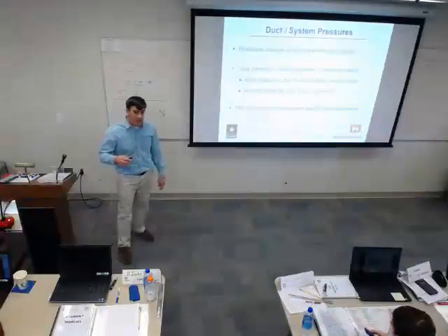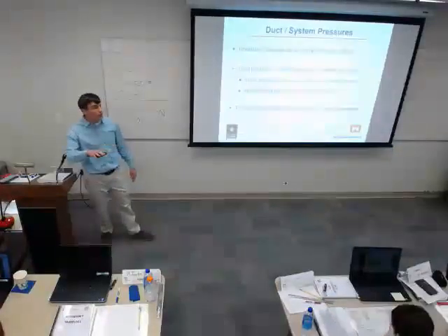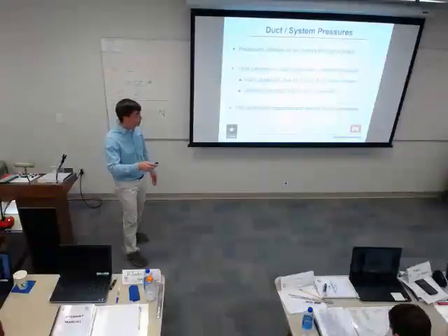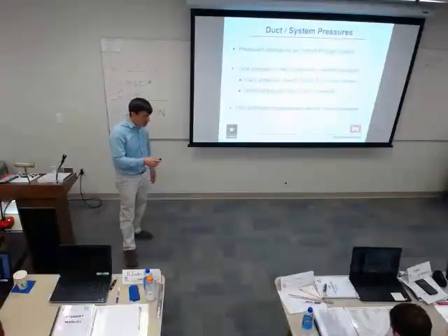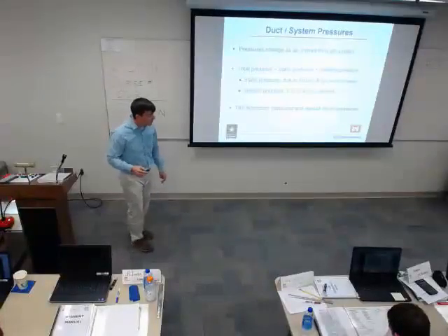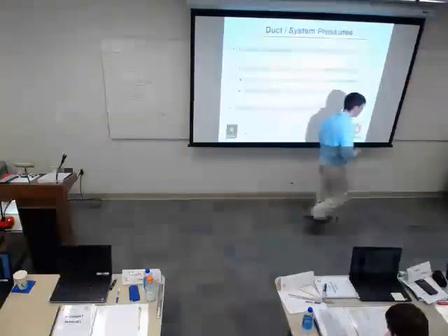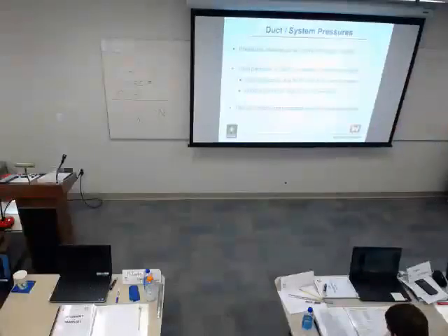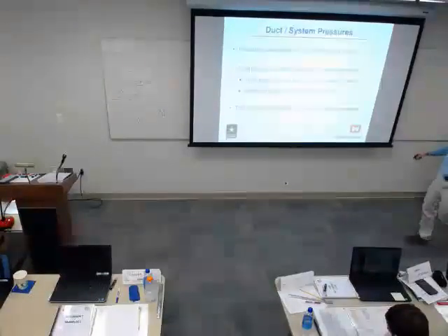Important to know that pressure changes as we move through the system. I'm going to show you a chart in just a second to hopefully help make that more clear. We talked about earlier, total pressure is equal to static pressure plus velocity pressure. Static pressure, looking at the pitot tube, is the one that's sensed by these little holes here. Total pressure is the one sensed by the impact tube. Okay?